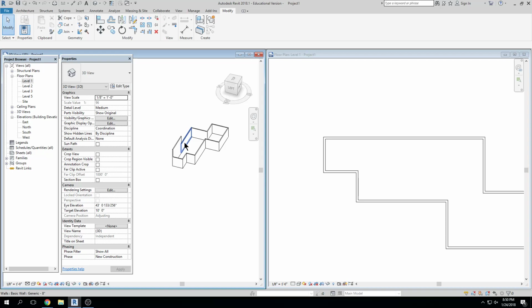Yes. So you're defining it. Revit doesn't really care what it's defined as, right? You could take this wall and define it to level 1, and it would essentially show like that in a building section, showing it going to level like that, which is not how it's going to work, right? It's going to stop right there, and it will function like that. But Revit will do whatever you want as a definition. Yeah. Okay.